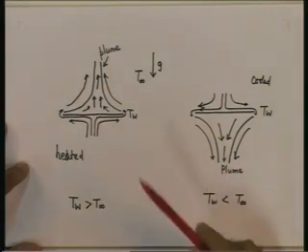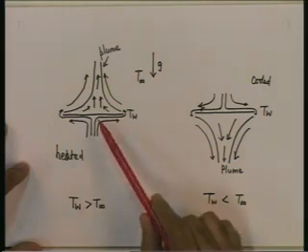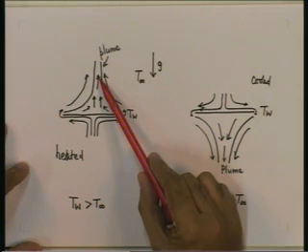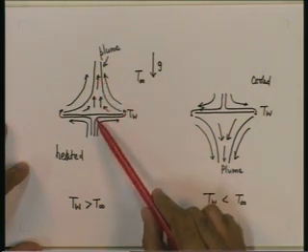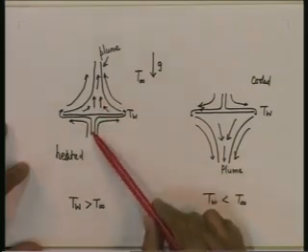And similarly, a cold surface facing upward will have a similar flow pattern compared to a hot surface facing downwards. Consequently, we expect to see two sets of correlations, one for a hot surface facing upwards and one for a hot surface facing downwards. These two situations would be applicable respectively to a cold surface facing downwards and a cold surface facing upwards.